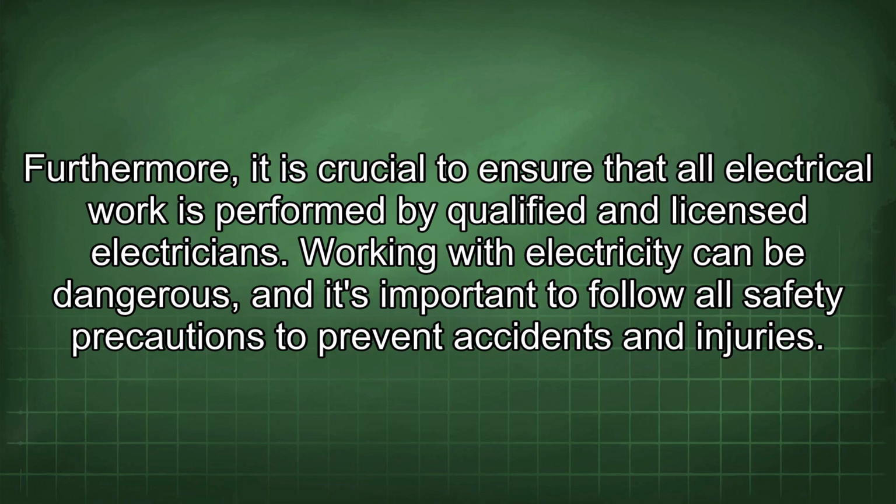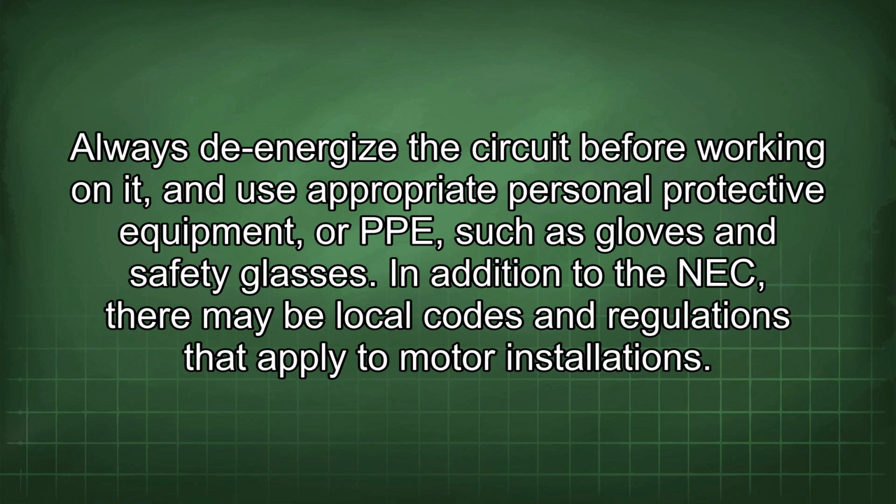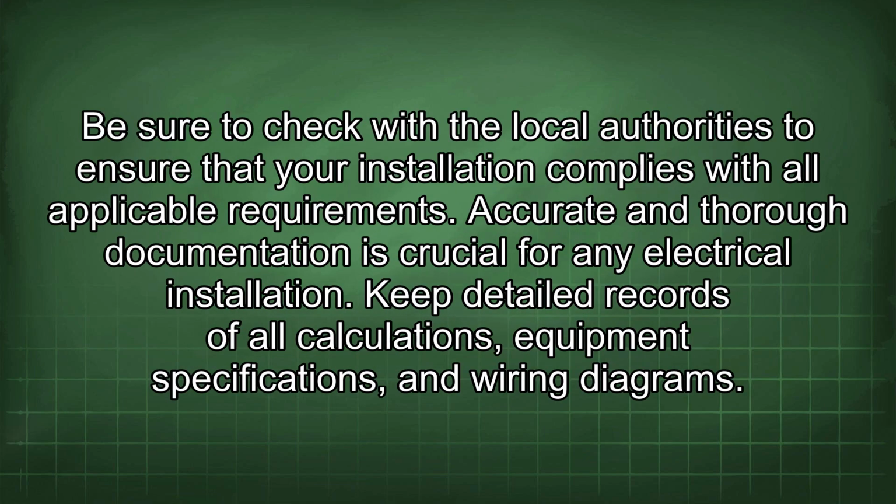Furthermore, it is crucial to ensure that all electrical work is performed by qualified and licensed electricians. Working with electricity can be dangerous, and it's important to follow all safety precautions to prevent accidents and injuries. Always de-energize the circuit before working on it, and use appropriate personal protective equipment, or PPE, such as gloves and safety glasses. In addition to the NEC, there may be local codes and regulations that apply to motor installations. Be sure to check with the local authorities to ensure that your installation complies with all applicable requirements.